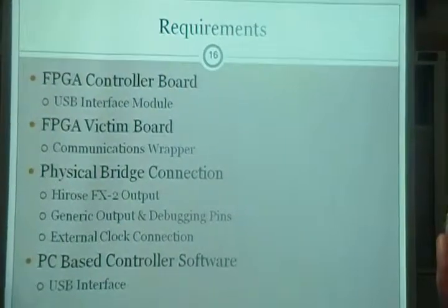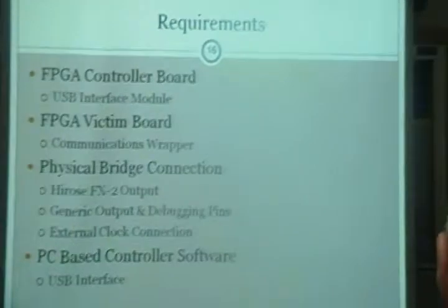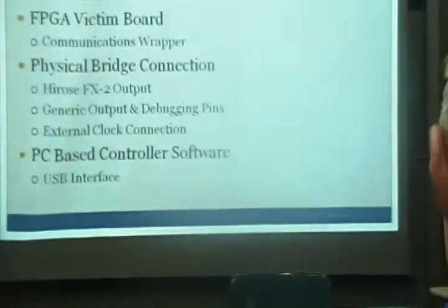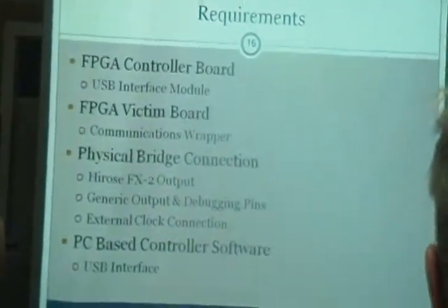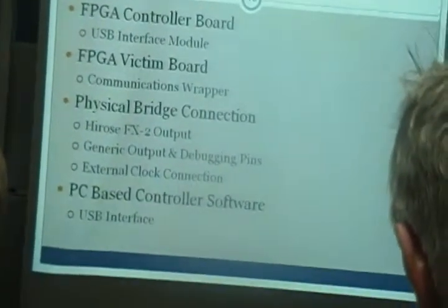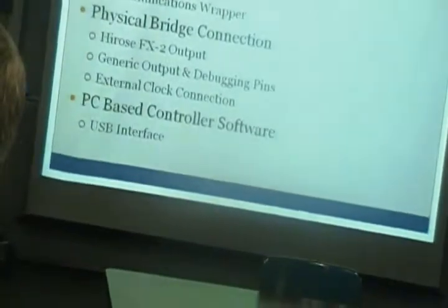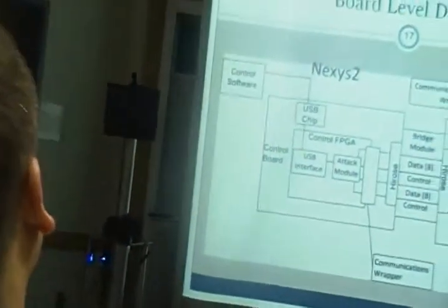physical connection between them. As part of that requirement, we needed to make it generic so that you could attack any device. So generic pins were added, as well as an external clock connection, so that you can clock either board at an external user-defined frequency. On top of that, we needed to modify the Sasebo PC-based control software. As I mentioned before, the chipset was different, so the driver would not be compatible.